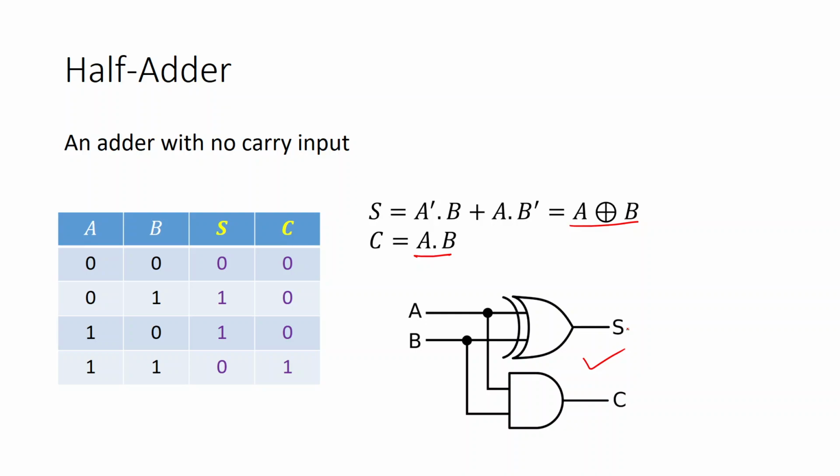So if you are asked to find out the half adder circuit, you have to first write down the truth table, from there you have to find an expression, and from there you have to draw the circuit. For any system, for any problem you have to understand how you can form the truth table. So for the half adder, you have to first understand the problem, what is half addition. Once you know half addition, it is an addition of simply 2 bits without any input carry. Basically here no input carry is there. When I talk about the full adder, you will see the difference.